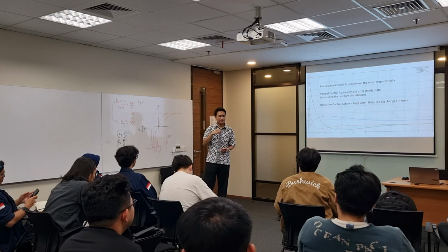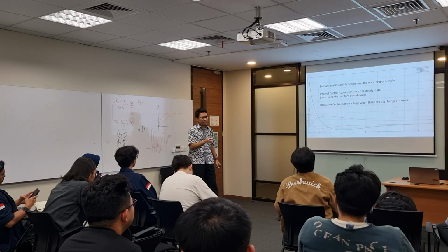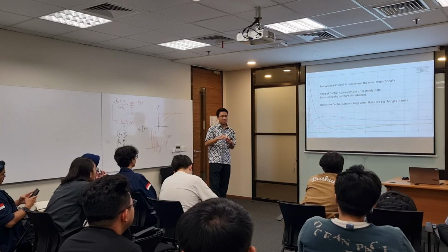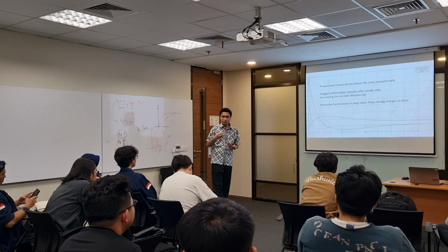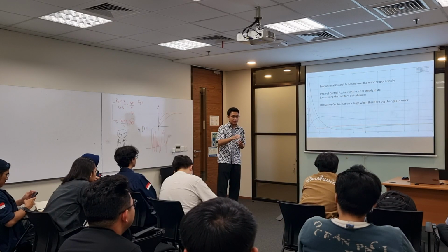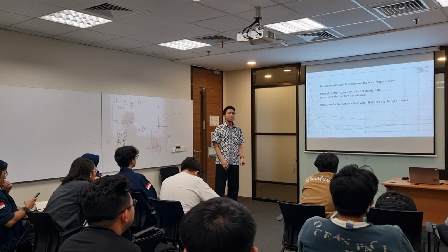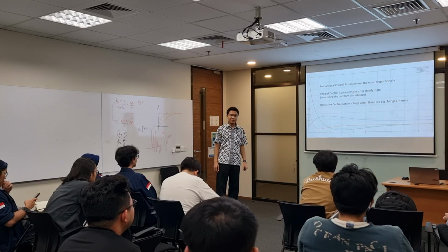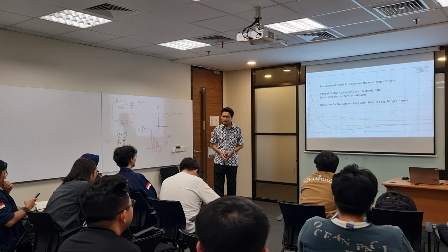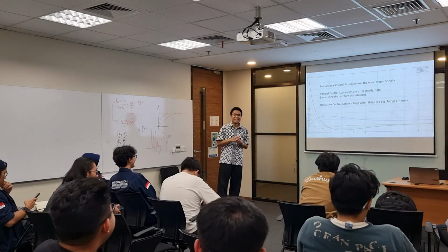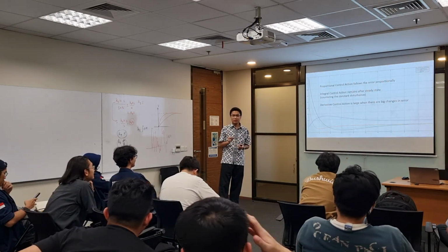Let's say you set it to be 60 km per hour. When you are cruising, you don't want 60, now 59, 65, 70. You don't want it like that, right? Which is why for cruise control, PI control is a must.